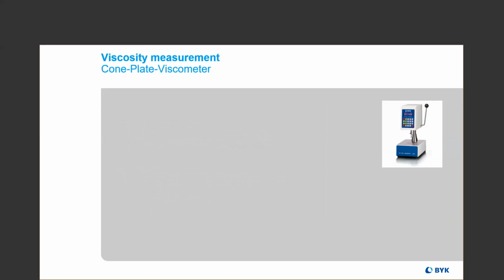The next example of a rotational viscometer is the cone and plate viscometer. These are for high shear measurement applications. We have the CAP 1000, and this comes in both a low and high viscosity version. They measure at just 2 different speeds. The 1000 version only comes with 2 speeds, 750 and 900 RPMs.